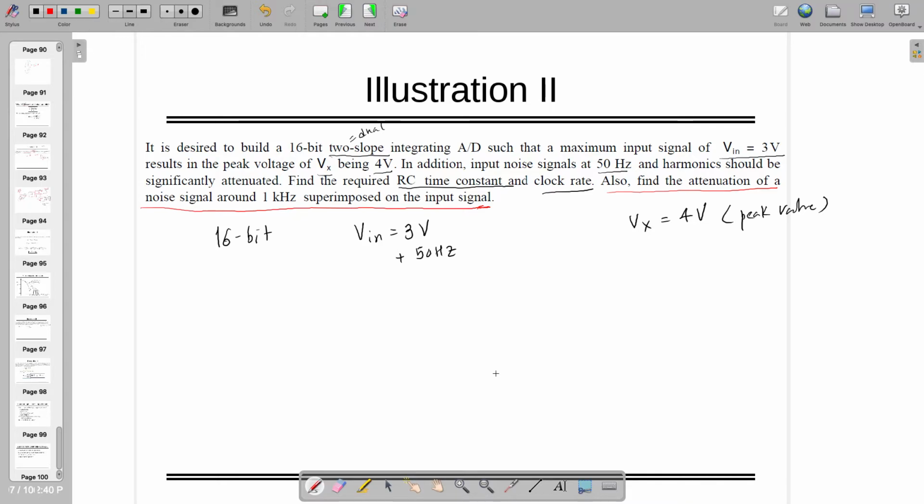So that's why we are increasing the frequency, to lower down the size of the inductor and capacitor. If the frequency is high, then that fluctuation would be less, and the frequency of that fluctuation would be the operating frequency.